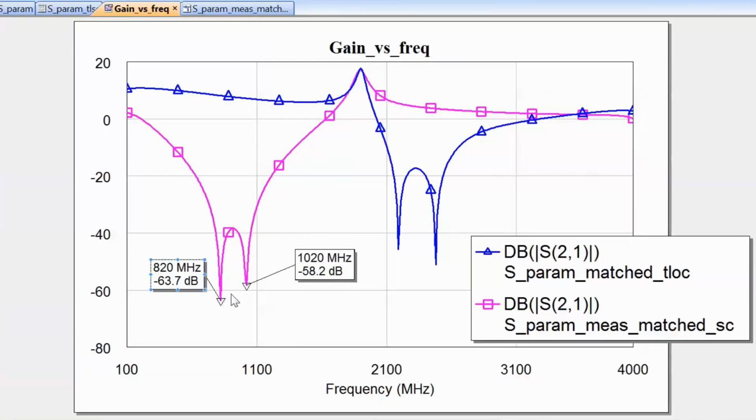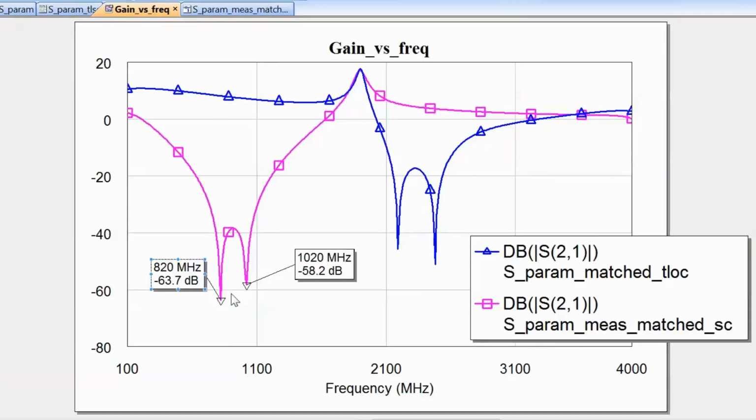So, since the electrical length of a stub is directly proportional to frequency, if a stub is 21 degrees at 1.9 GHz, it'll be way less at 820 or 1020. And for the output stub, which is only 12 degrees, then that will be a tiny electrical length at lower frequencies. So definitely we can't possibly blame these two troughs on a quarter wave transformer effect.